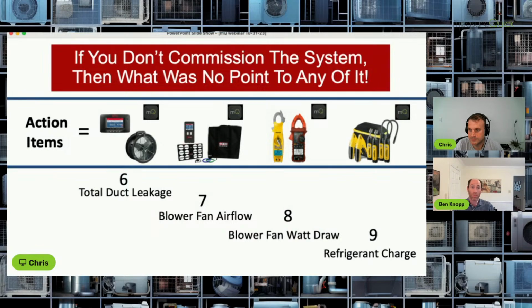Like we're doubling the moisture load and reducing the sensible cooling load, so we don't need to run the AC as much. And that's trouble unless you can calculate how much water is coming in and you know you have the equipment to remove it all. And that's why the dehumidifier and the ERV, they both play a role in handling the humidity in this home. Yep.